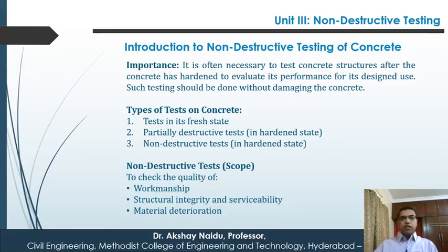So, introduction to non-destructive testing of concrete. Now, importance: it is often necessary to test concrete structures after concrete has hardened to evaluate its performance for its designed use. Such testing should be done without damaging the concrete. So, the concrete has to be tested after the structure is built, after say many years, 3 to 5 years. Now, we have to ascertain the strength of the concrete without damaging the concrete structure. So that is when non-destructive testing is used.